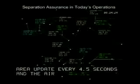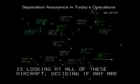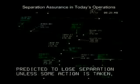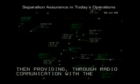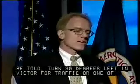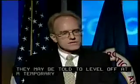So what the controller is doing is looking at all these aircraft, deciding if any are predicted in conflict, in other words, predicted to lose separation unless some action is taken, and then providing clearances to the pilots through radio communication. For example, an aircraft might be told turn 30 degrees left, vector for traffic, or one of those climbing aircraft may be in conflict with a level aircraft or another aircraft. They may be told to level off at a temporary altitude while the conflict aircraft passes over.